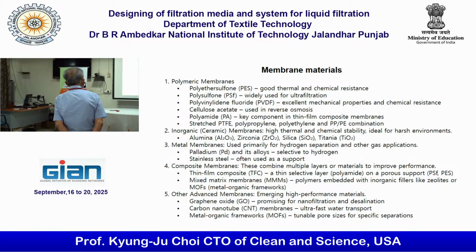Now, I'm going into the membrane material itself. Polymeric membrane: polyether sulfone, PES. Good thermal, yes, the thermal is important, PES. The last one, PTFE, of course. As far as thermal is concerned, this is a lot better than any other material. Polysulfone, polyvinyl, PVDF. This is quite an important material.